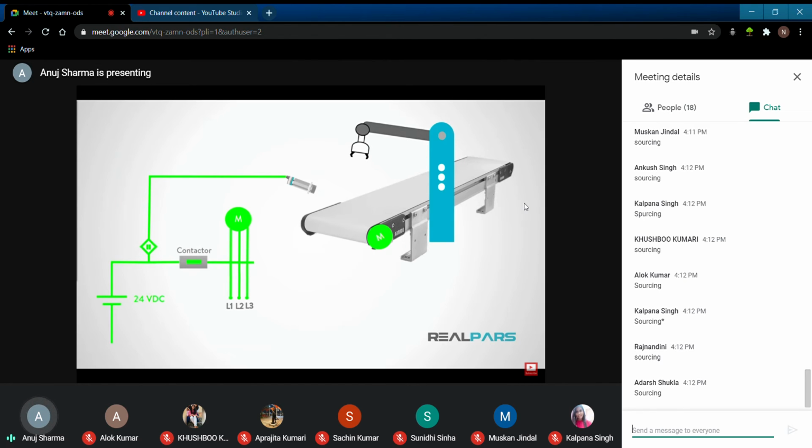The common trait of all discrete DC sensors is that they have exactly 2 operating states, on and off. A discrete DC switch, as in this diagram, is on when an object is in proximity to the switch and its internal contact is closed, forming a complete circuit and allowing the flow of electrons. When the object is moved away from the proximity sensor, its contacts are opened again. The circuit is broken and the flow of electrons stops. The state of the switch is off.